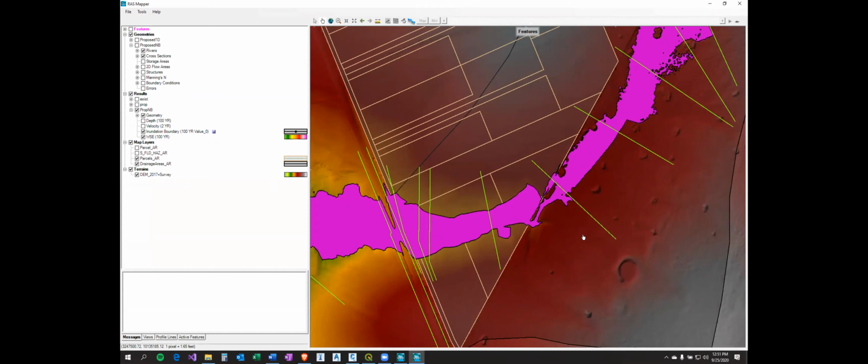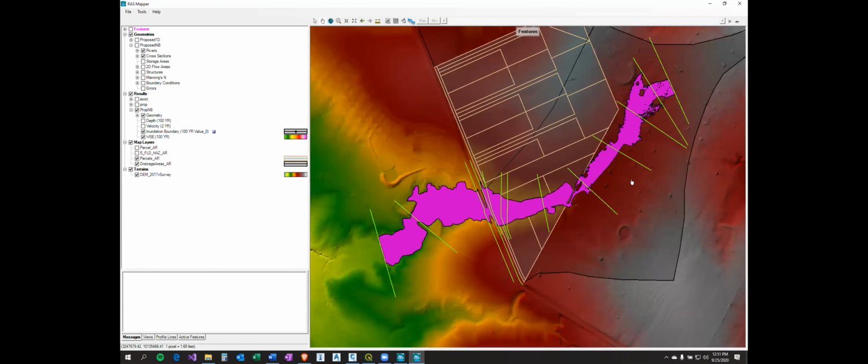Actually, what I'm doing is I'm teaching a class at ACC. I'm doing a little bit of research with the University of Texas that kind of dovetails into what Adam was showing, and getting tugged on by the National Weather Service to do what they call base level engineering conversion to flood inundation mapping. So it's programmatic interaction with the stuff that Adam's showing. I'm trying to do all this with Python code without actually touching RAS itself. Let RAS run in the background.